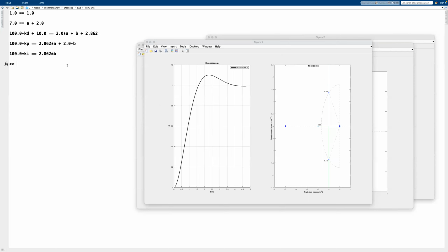So that's a strong assessment that we did here, because it eliminates the possibility of instability, which is nice. But we don't know about the residue poles, where they are, if they are entering the dominant region, or if the zeros are entering. That we don't know. So what we want to do is solve this whole set of equations in terms of Ki, which is possible to do by pen and paper, by hand.